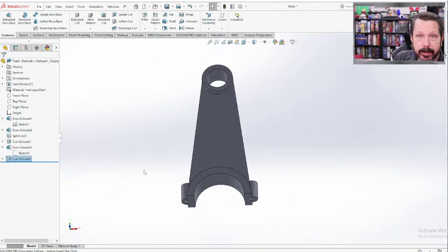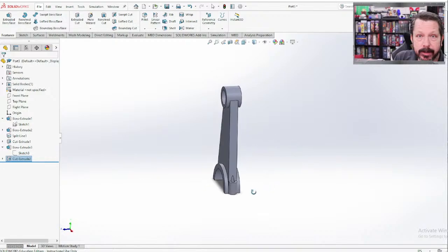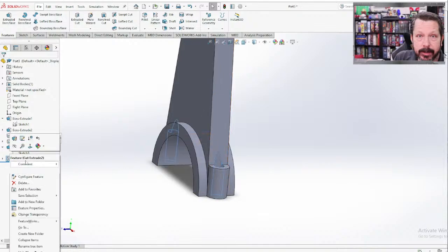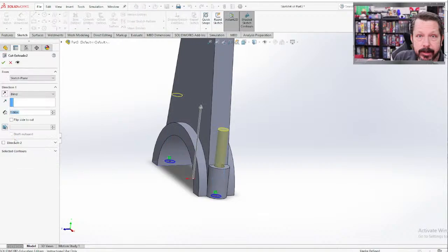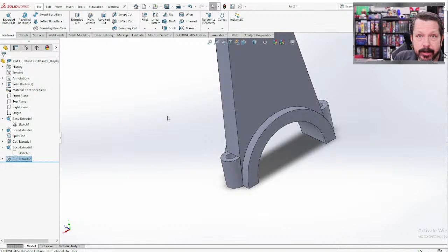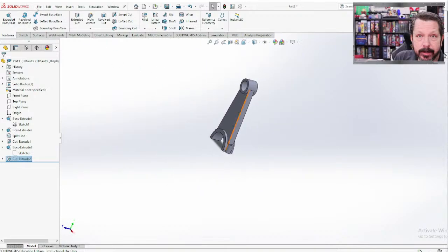All right, so we could spend some amount of time working on getting this thing just right. All right, but let's assume that we don't want to. Actually, you know, this little cutout right here, that part might give us some problems later on. So let's actually edit this guy so that we do extrude up to surface, that surface. So might still have some issues. We're not going to be too worried about it. Now would be a good time to save.